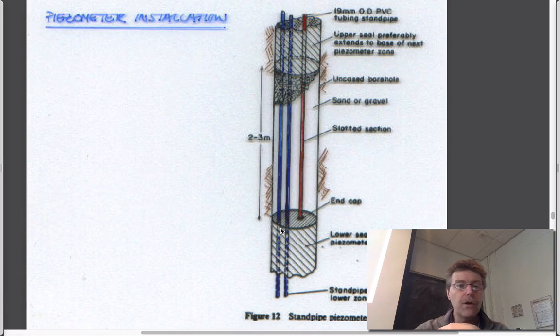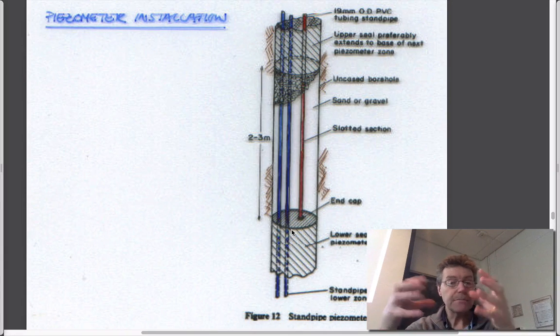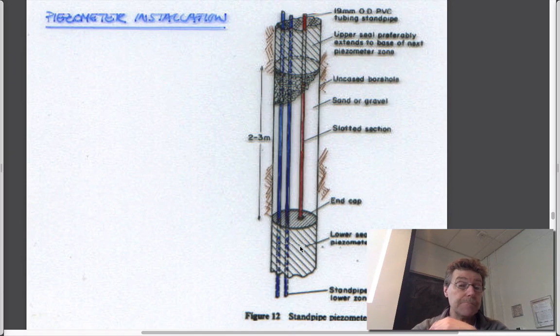You drop them down the well, they go down to the bottom, the lacquer dissolves off, and the bentonite, a swelling clay, expands and basically makes a seal. You drop a piece, maybe 100 feet, maybe it's 800 feet deep. You can certainly do these down to 800 feet.